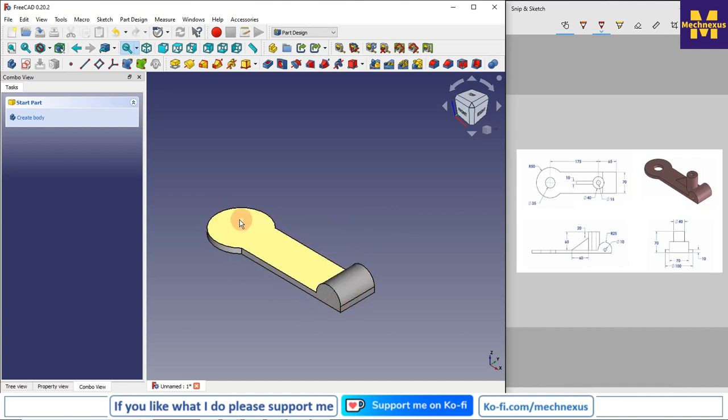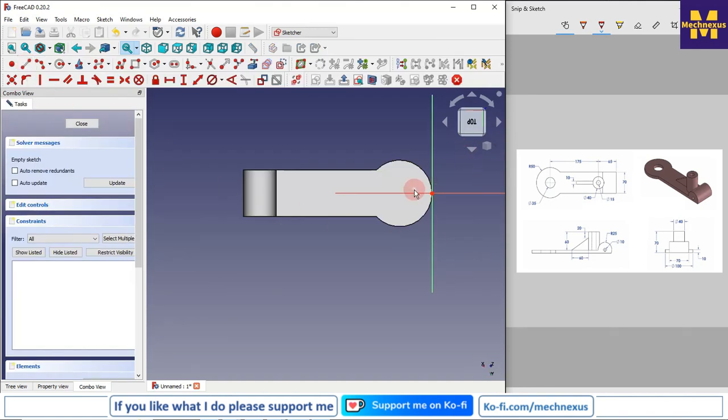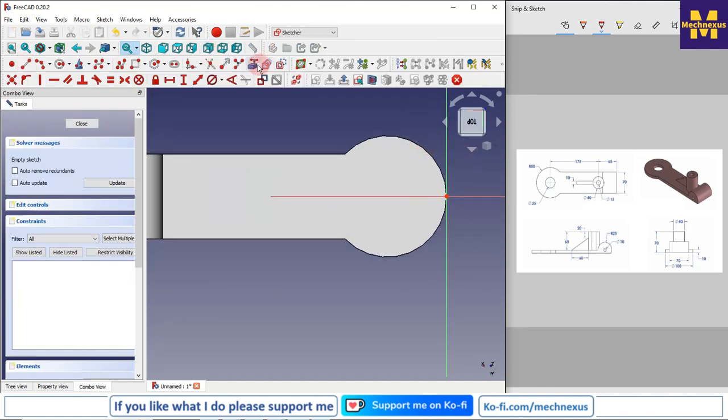We will adapt the hole here and hole here. So I will select this face and I will create a sketch, and I will project my outer edge, and now this is the diameter 35, so I will select the center point and make a circle.